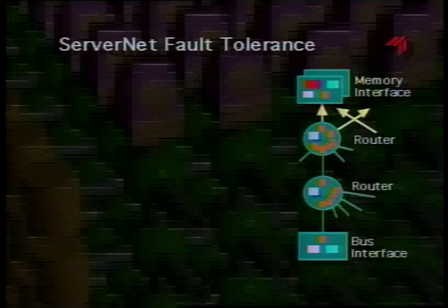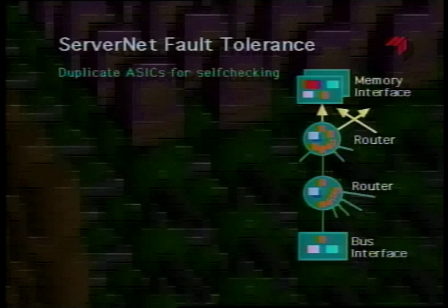The processor interface chips are duplicated for self-checking, and they may also connect to duplicated CPU chips so that if there's a failure of any CPU or processor interface, the two copies will disagree and comparators are used to detect the failure immediately. The diagram also shows the address validation and translation tables that are critical for containing faults in the I/O system. The AVT tables prevent these faults from corrupting large regions of main memory.